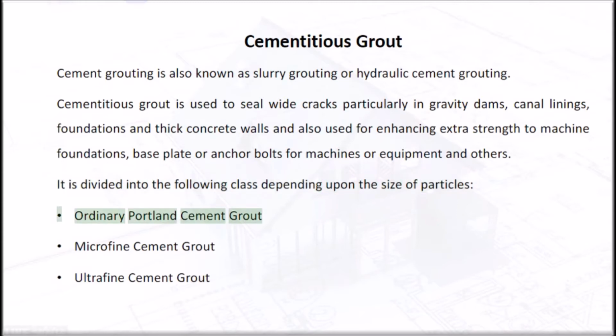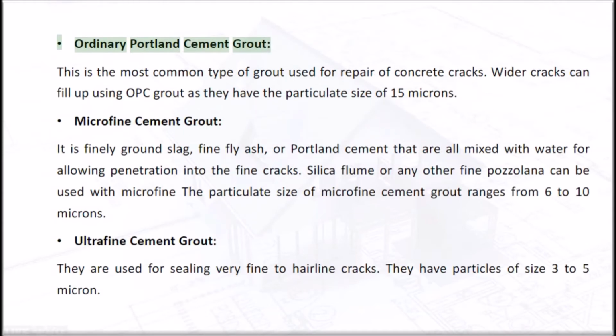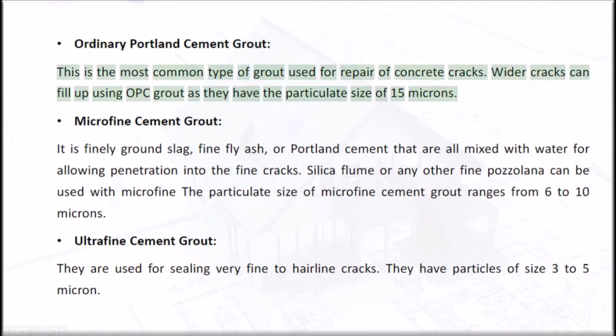Ordinary Portland cement grout, microfine cement grout, ultrafine cement grout. Ordinary Portland cement grout is the most common type of grout used for repair of concrete cracks. Wider cracks can be filled using OPC grout as they have a particulate size of 15 microns.